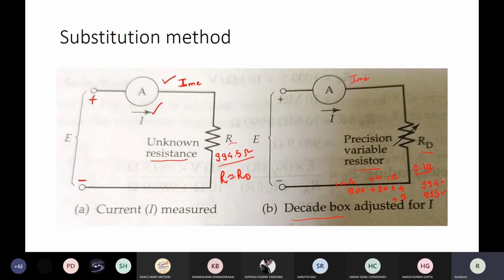Because that is where, let's say this has indicated 1 ampere. This can never show 1 ampere, not because the ammeter is faulty. Are you understanding? Yeah. It is because the resistance cannot vary with this precision. So this problem is associated with the precision resistor, not with the ammeter. Yeah. Now with this, can you go ahead, what is your idea?